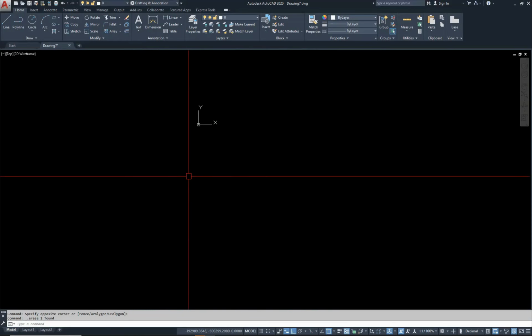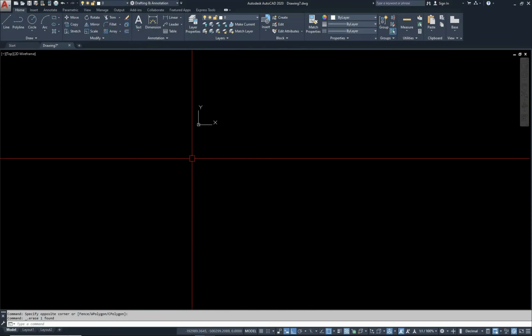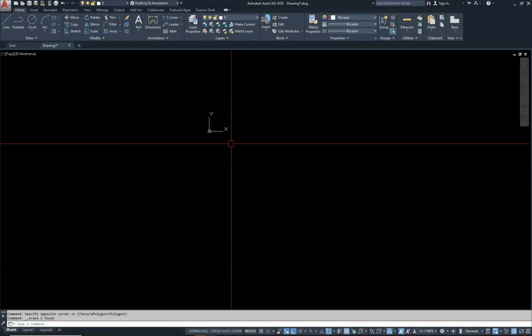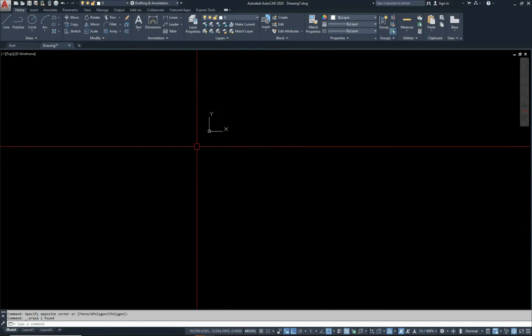So before this, the most important thing is our units. Because AutoCAD gives us a chance, as I told earlier, to work on anything according to scale and accurately. So for units, simply type UN, units, and then hit spacebar, enter, or right click, any of the three options will activate your command.